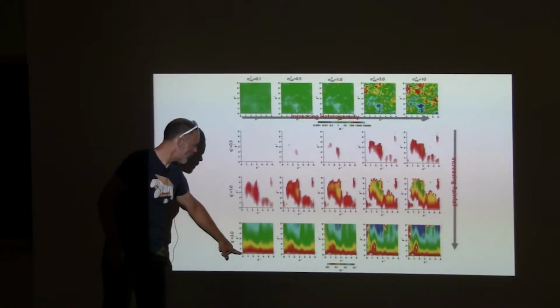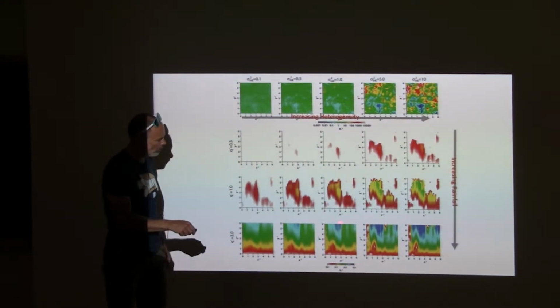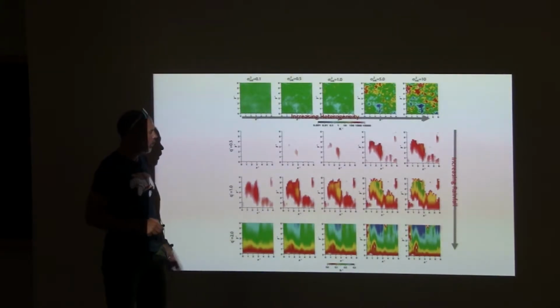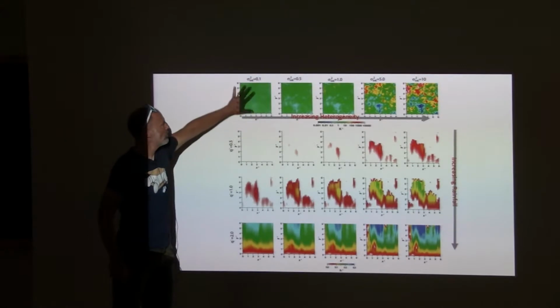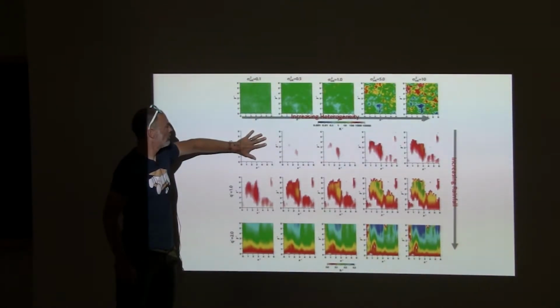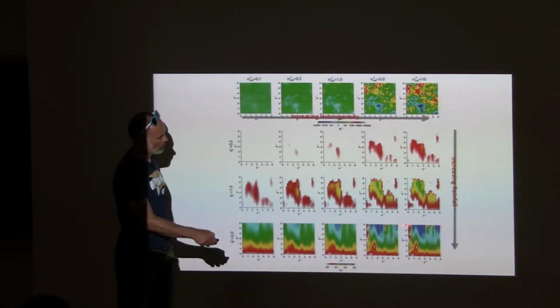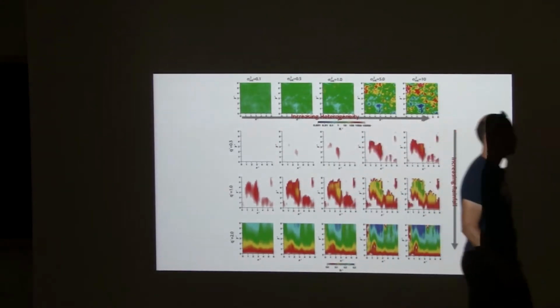Our flow is from the top of the hill slopes here, the bottom of the hill slopes here. Blue is deeper runoff, deeper water. Red and white are lower ponded water. We see down here, low K, low variance, low rainfall rate. We have almost no runoff generated. Here we have high variance, high rainfall rate, and we're ponding and generating some pretty interesting distributions of runoff.